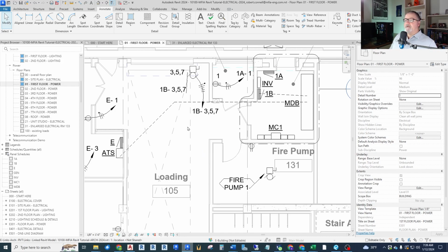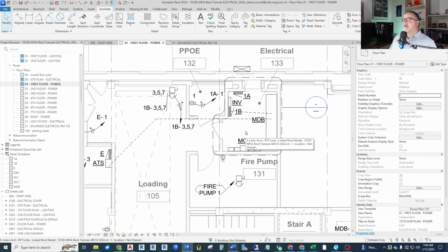However, now that we can do this in 3 dimensions in Revit fairly simply, that's very helpful for the design team for coordination. So let's get into how we do that, now that we know why. First thing you'll want to look at is, what views do we need to do this? Doing this all in the plan view is not practical. So we need more than a plan view. We'll need some sections through our building so that we can deal with the vertical pieces of conduit. So let's do some sections.